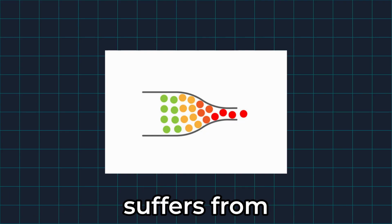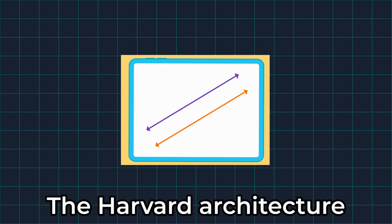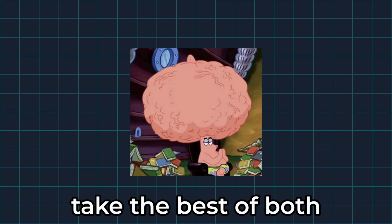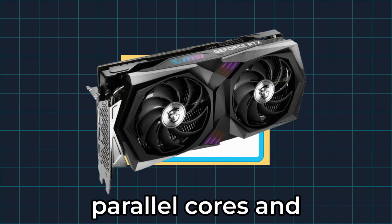So to wrap it all up, von Neumann uses one shared memory and therefore suffers from a bottleneck, but it is still great for general computers. The Harvard architecture splits memory for parallel access, so it is perfect for embedded systems or microprocessors. Modern processors take the best of both worlds, forming contemporary architectures alongside parallel cores and coprocessors.